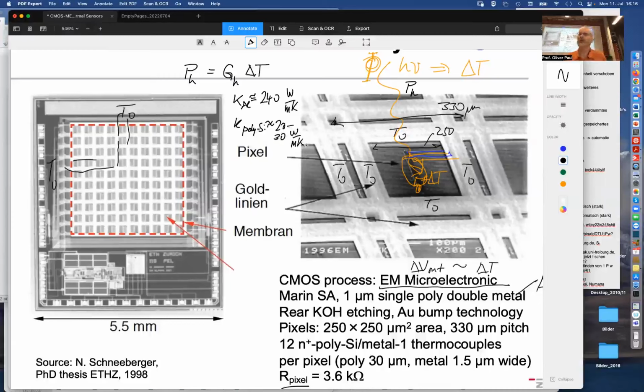So making the aluminum as small as possible makes the thermal resistance larger, or the thermal conductance smaller, so that delta T can be larger for a given heating power. So that's all consistent.